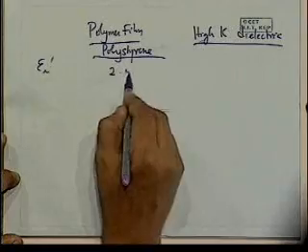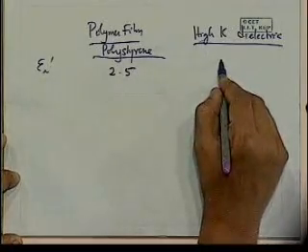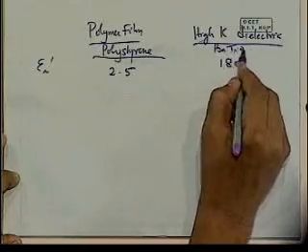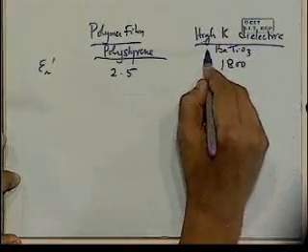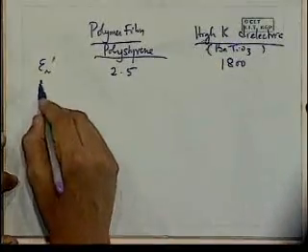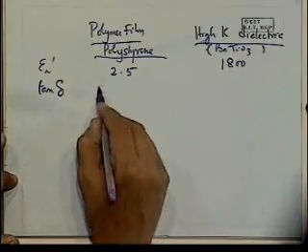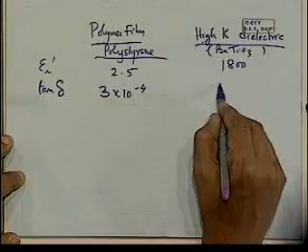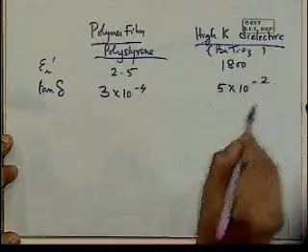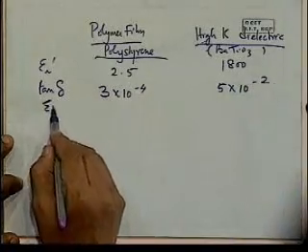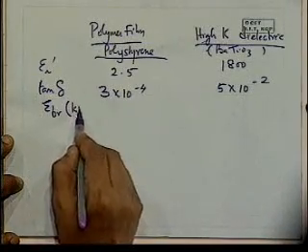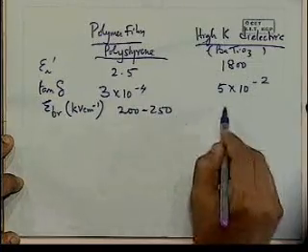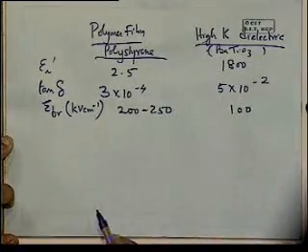Permittivity: low for the polymer, and for the high K dielectric maybe something like 1800. This is something, say, that's based on barium titanate. Tan delta losses: very low in the case of polystyrene, relatively high in this high K dielectric. Breakdown field strength in kilovolt per centimeter: 200 to 250 for the polymer, about 100 there.